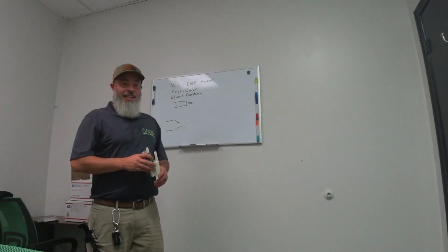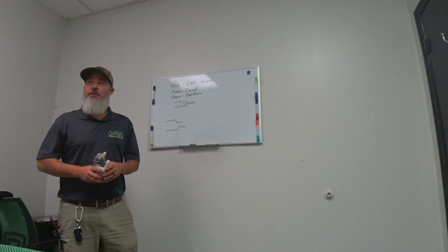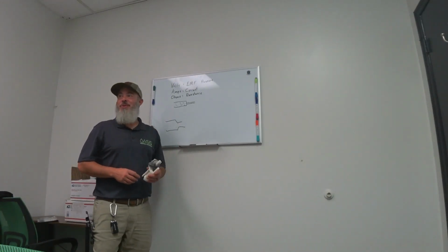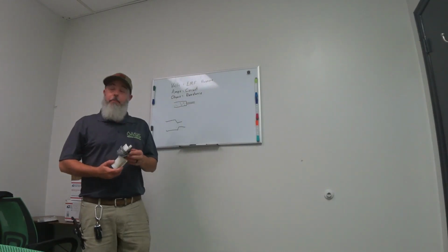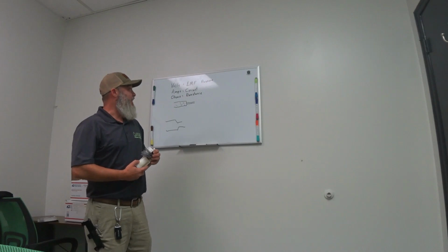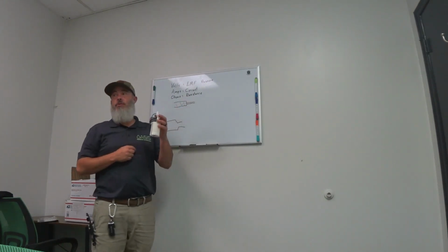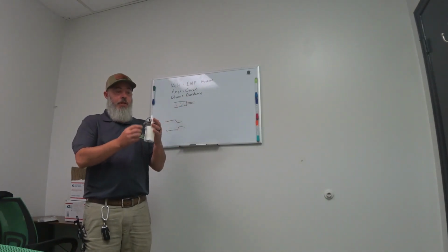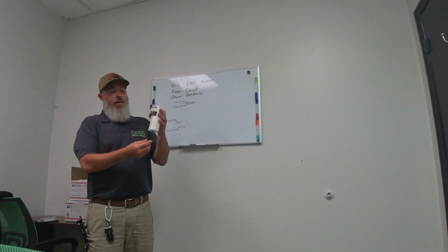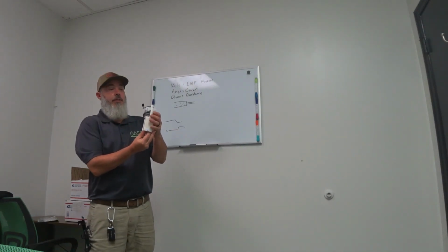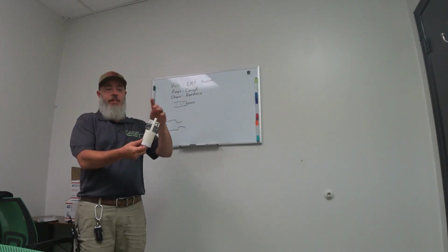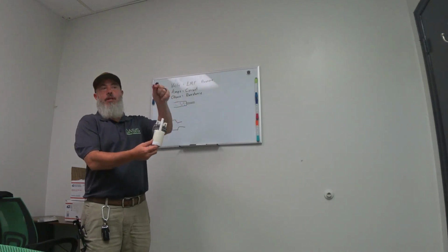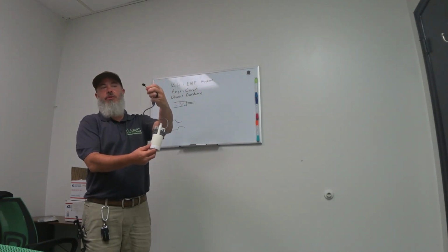In that situation, experience will tell you, oh, float switch, just go ahead and change it out, because you've seen this a bunch of times. But we use resistance to test this float switch right here. When it's full of water, you pull this off right here and look in there, you see that sump is full of water. You just cut the machine off. This one goes up to the board. There are 2 wires right here, a black and a red.